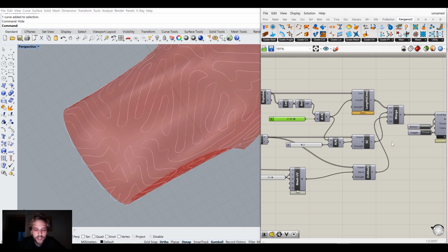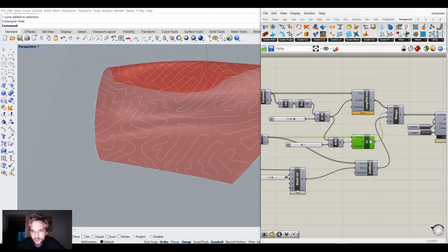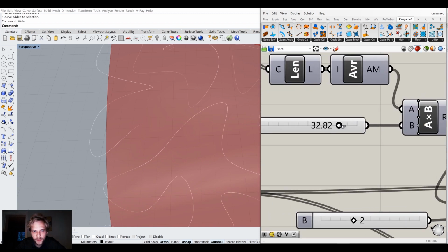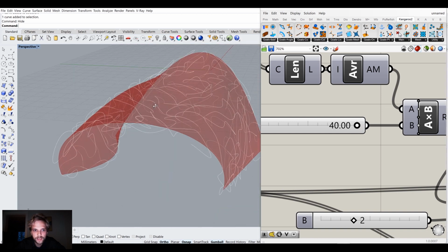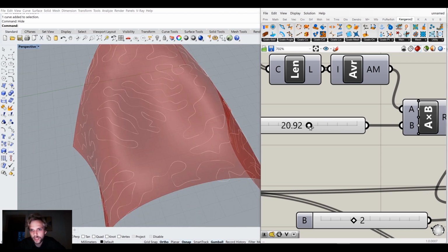So collisions are pushing it out from the boundary. Collision detection overtakes the on mesh component here, and they start extending out of the surface. If I keep increasing it, they will go out and out more and more until they kind of mess up, right? So we don't want to do that.